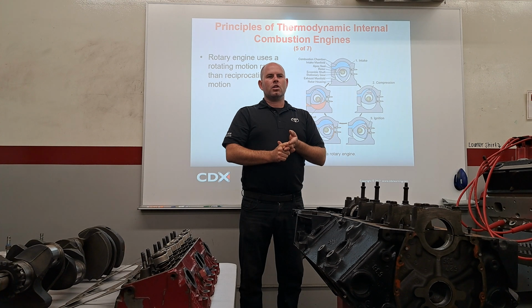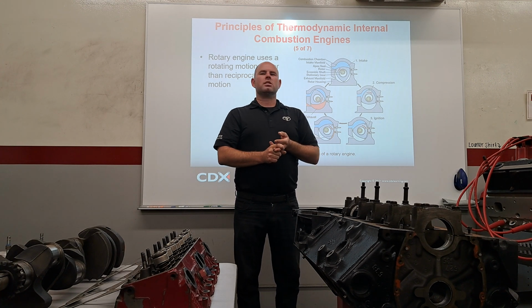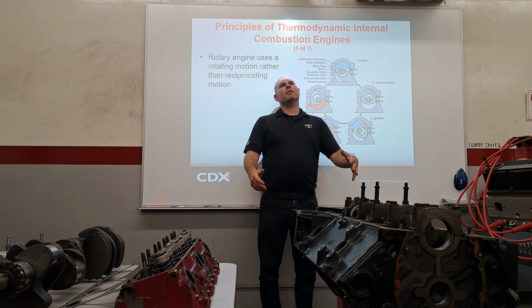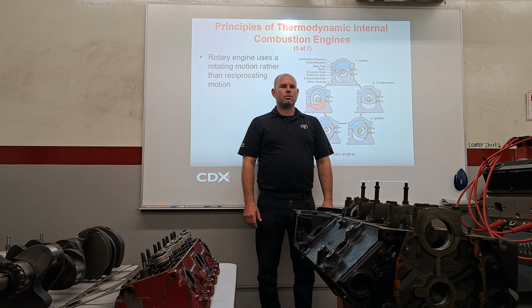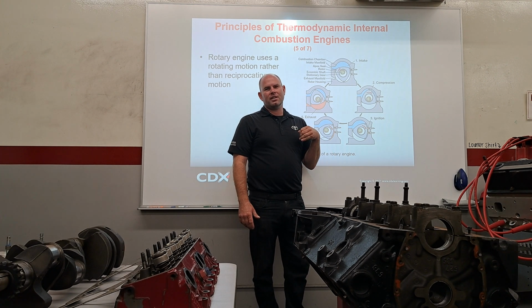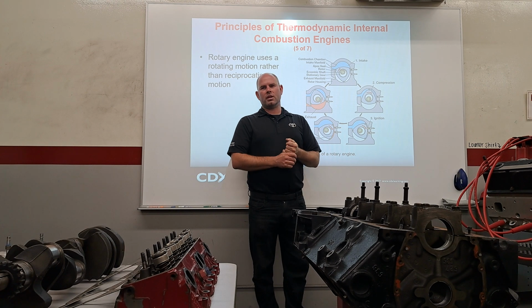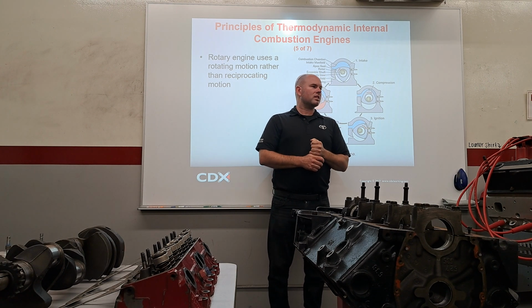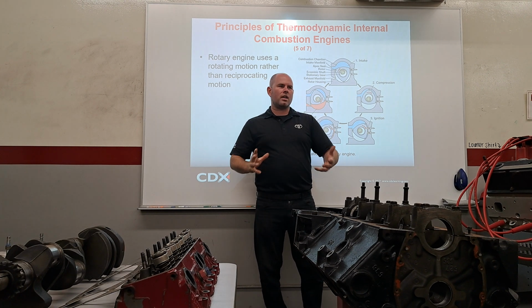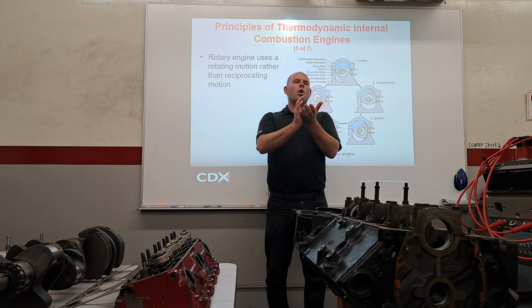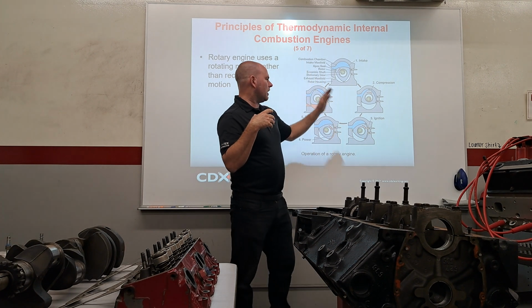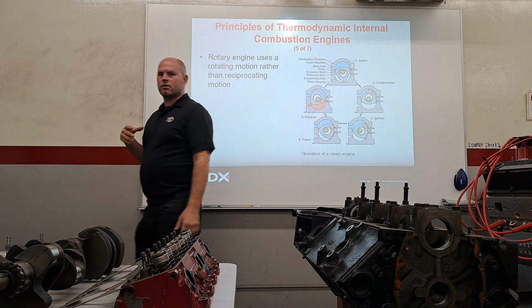You know diesels don't do that. This is the number one thing everybody knows about a diesel: it doesn't have spark plugs. Yeah, that's true. And then somebody said, but it has glow plugs. And it's like, yeah, but that's not really important, because there are lots of diesels that don't have glow plugs, and a whole bunch of clapped out diesels where the glow plugs don't work. So a compression ignition engine is where they make so much compression that the compression alone will start the combustion. Kind of make sense? So our focus is going to be on spark ignition. Make sense? Because that's what we do.